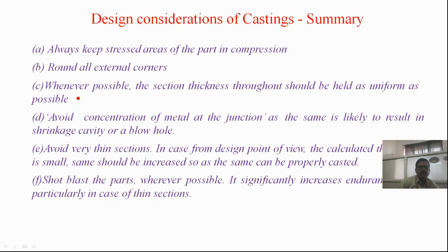So the summary: always keep stressed areas of the parts in compression, and all the external surfaces or corners should be rounded.